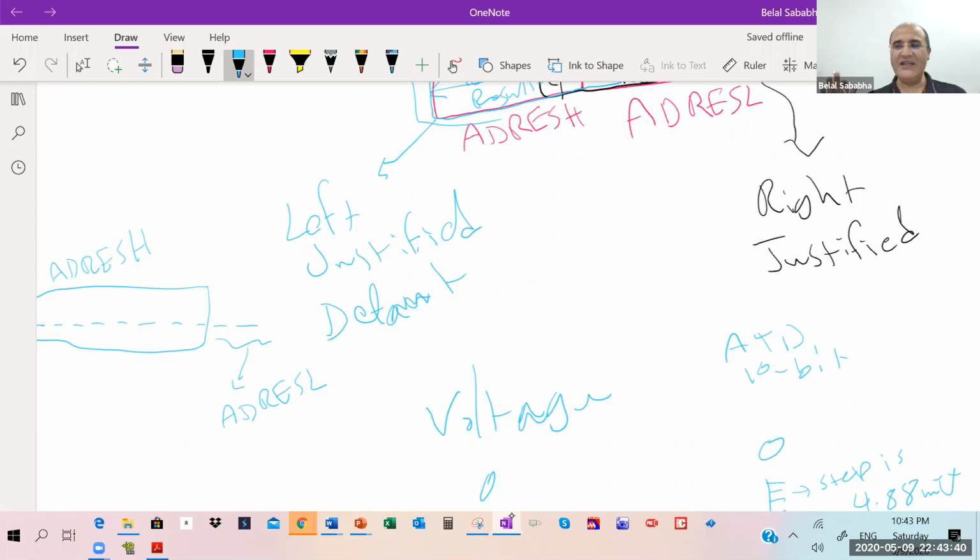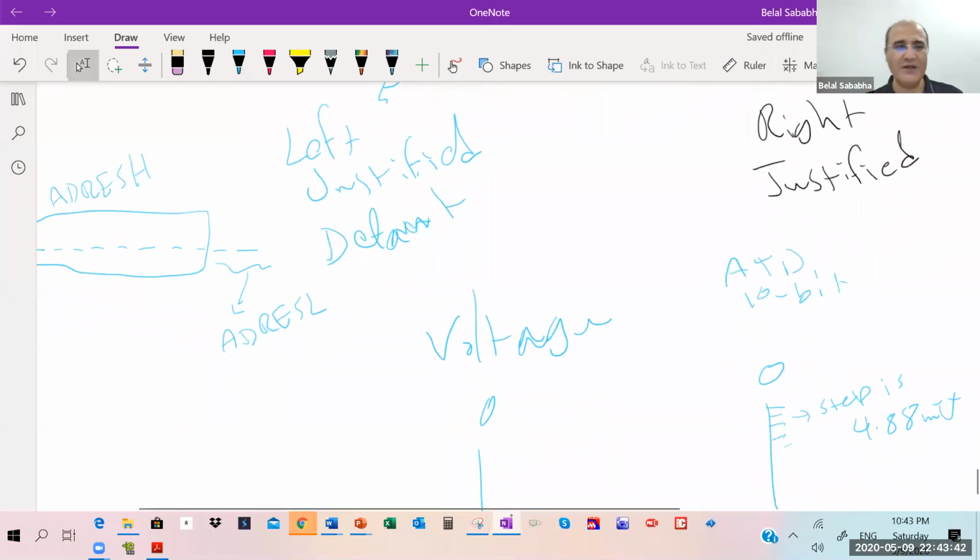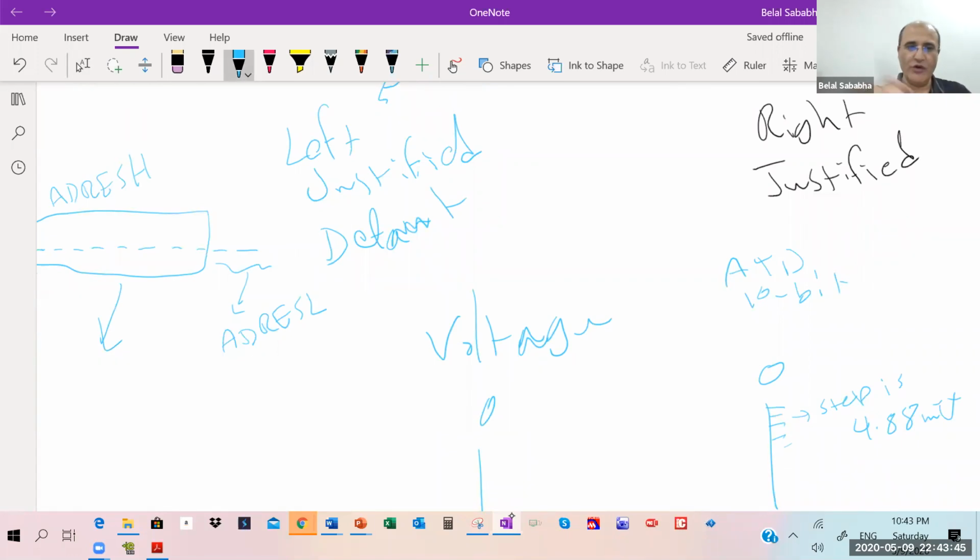In some applications, you can take these as they are, and without reading the low register you can save another instruction. See what you saved: you didn't set that bit, you kept the result at high, and you didn't read the low bits, ignoring them and pretending they are 0 without hurting your reading. The difference here could be from 0 0 up to the maximum 1 1.